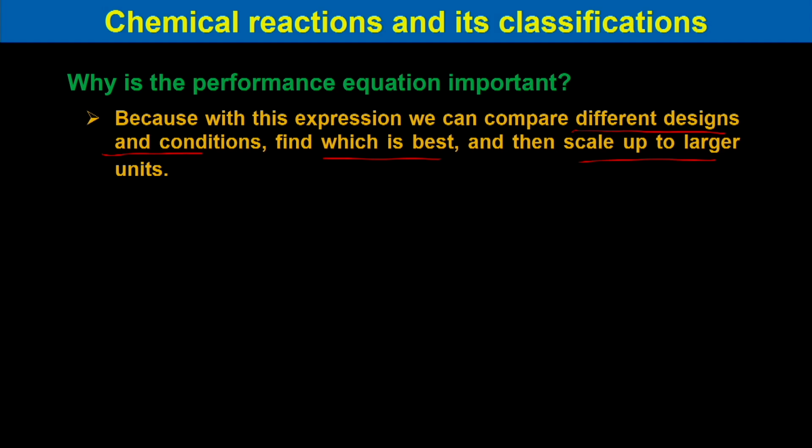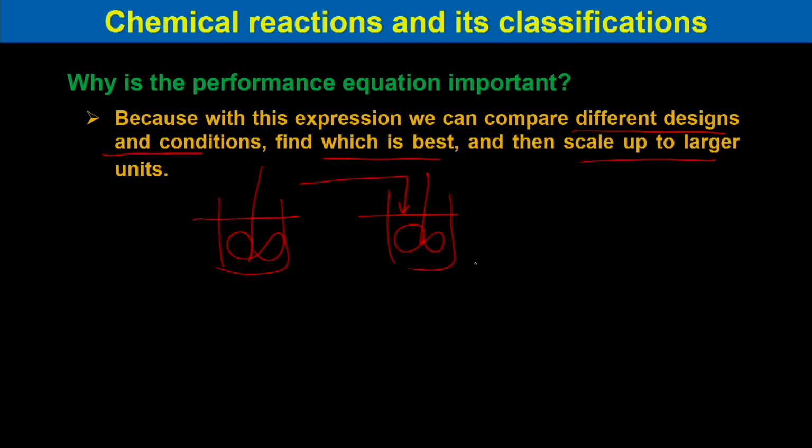Let us introduce them a little bit. You have the batch reactor like this, where you dump the material and stir it. There is no input and output, we call it a batch reactor. Then you have flow reactors, one of them the CSTR, where you feed the material, stir it, and there is a constant output from the reactor. This is called the continuous stirred tank reactor. This is CSTR, this is batch, and another idealized reactor is the plug flow reactor.